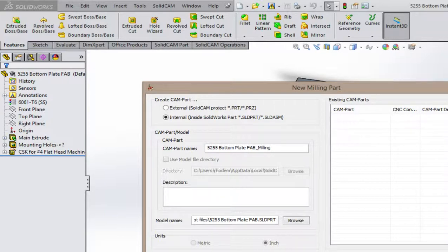This is going to be key here, is getting your units right. If you pick metric now, the units are going to be metric forever and you can't change it. I know that sucks, but it's the way it is. So it's very important that you get on the inch units because our machines are in inches and everything we measure is in inches. You must do it here. Notice that this is grayed out, but it's selected on inch.